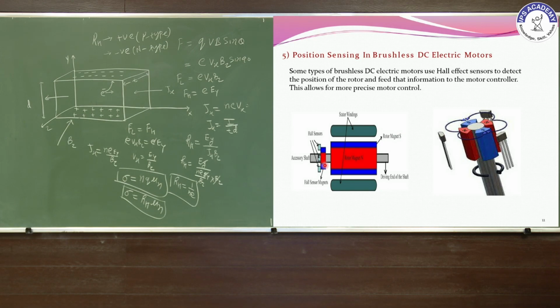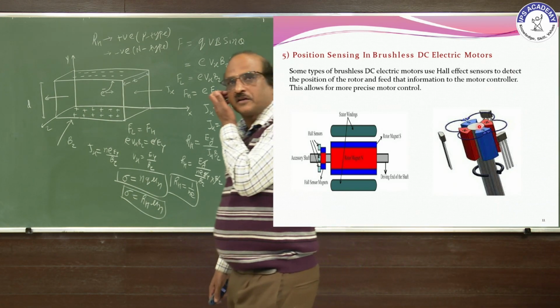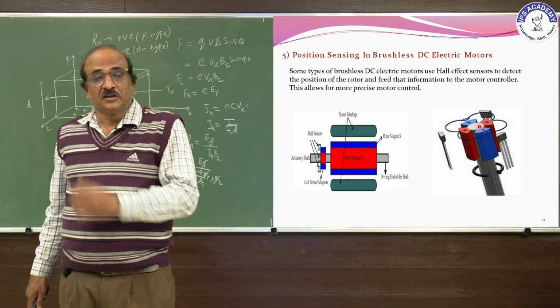So it always shows the position of the north and south of the magnet. We have enlarged this image of the commutator, and there are 3 Hall sensor ICs there. If the north pole is coming in front of the sensor, it gives the signal to the stator winding, and the stator winding again produces such current that north repulsion is always there, and it maintains the motion. So it is used in high speed motors like BLDC, like drone motors.